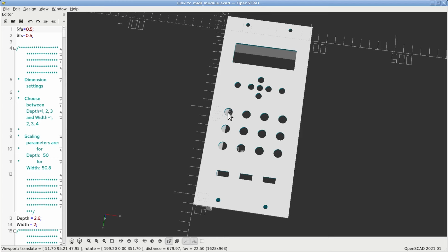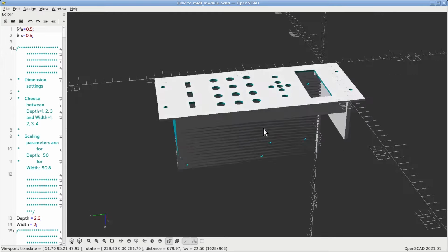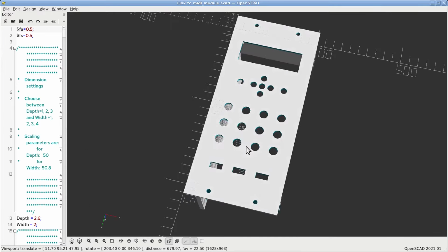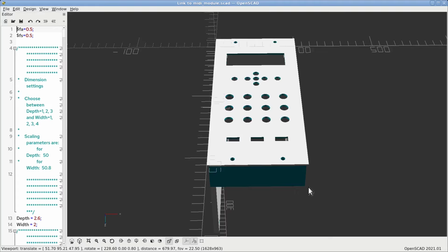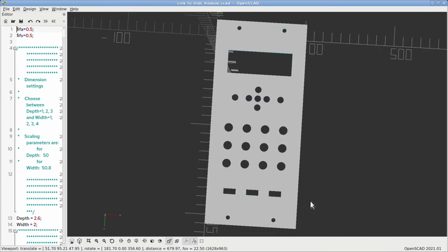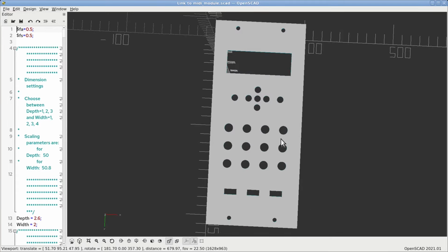Follow 12 holes that will be used for 12 distinct jack sockets. In the first row we will have the control voltage for modifying the pitch of a VCO, the velocity control voltage, and the gate and trigger signals, which are similar to those we have in the keyboard module. The remaining 2 rows of jacks will provide control voltages to handle the various capabilities of the synth.